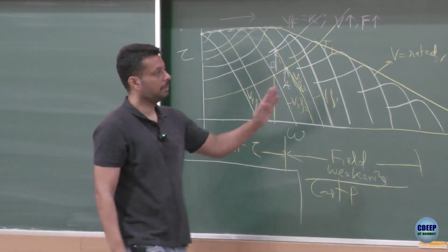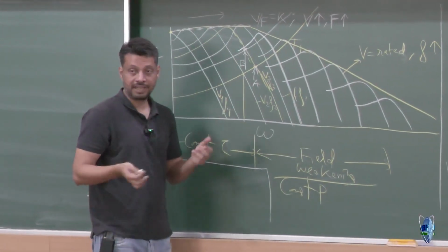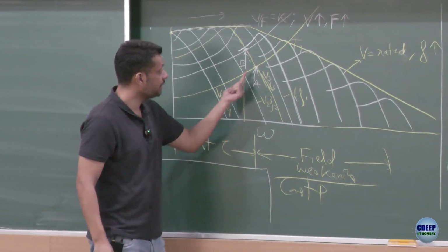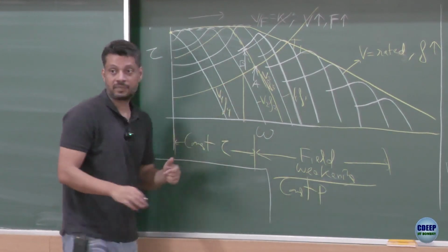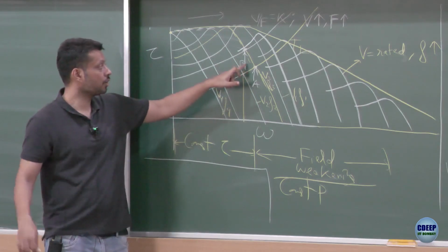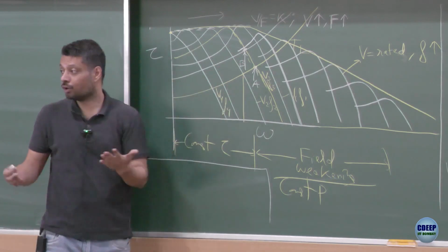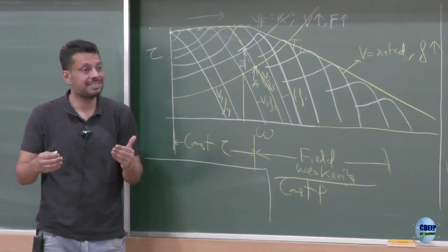So inherently you can do it. How can you do it? If you are observing it, you can change the frequency. So for example, now you see you are operating at point A, right? Suddenly somebody turned on 2 more bulbs, you have moved to point B. Your speed has reduced. You know what to do. You have to increase the frequency a little bit more.